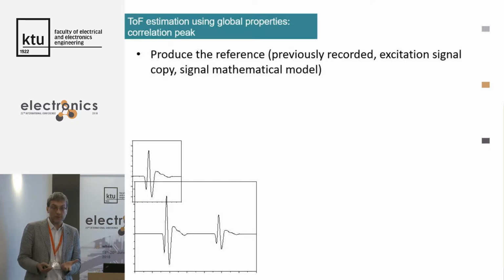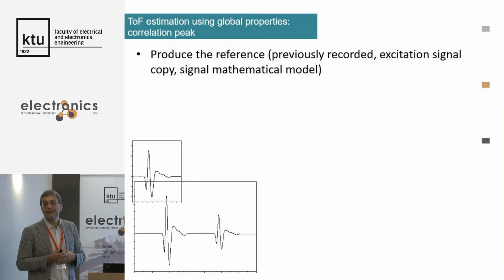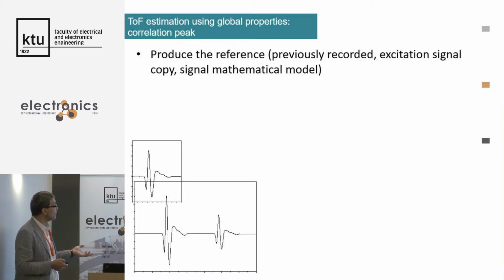So what else can be matched? We have made the shape of the filter ideal, and it matches the shape of the signal spectrum. What remains is the phase. For the optimal filter, we do not care about the phase. With the matched filter, we want the phase to be opposite of the signal phase. This is equivalent to having the complex signal and its complex conjugate. If you multiply the complex signal and its complex conjugate, you get rid of the imaginary part, and actually you get the magnitude of the signal. So this is the idea behind matched filtering.